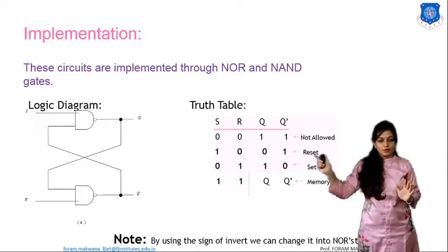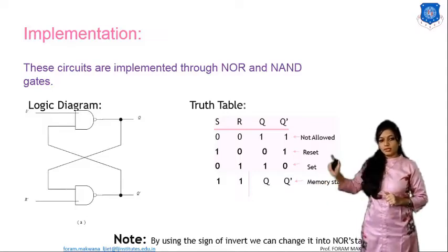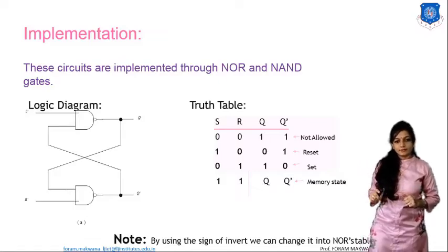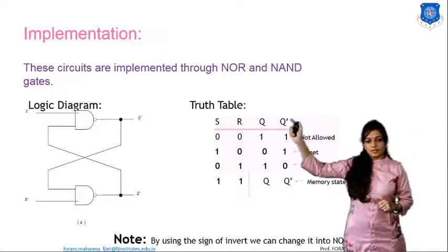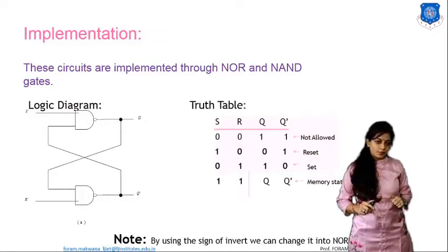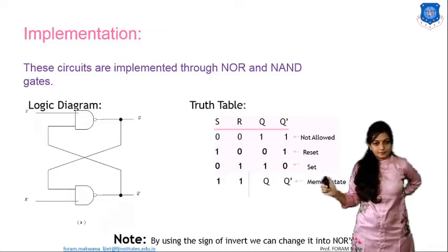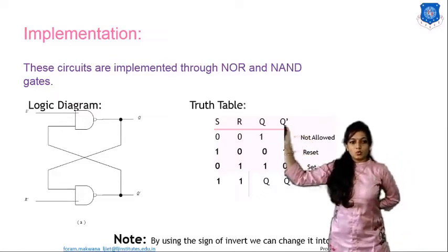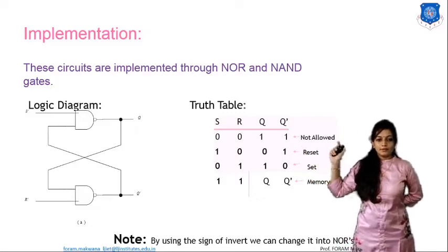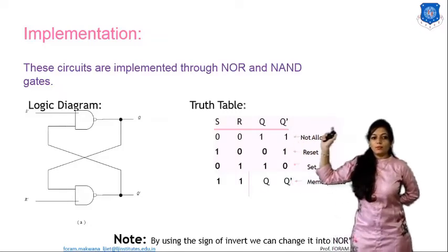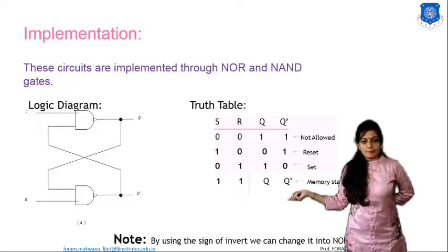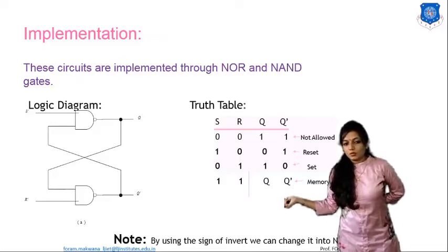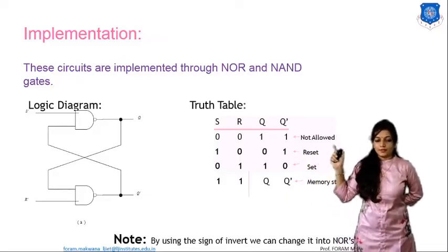Alright, to the input of one of the NAND gates. So S is equal to 1. What are we getting over here? The flip-flop is going to be reset. Why? Because that output Q becomes 0. Right? But whenever we apply over here S is equal to 0, and what will happen? If S is equal to 0, Q will be 1. And if R is equal to 0, Q bar will be 1 as well. That we have already considered. Alright?